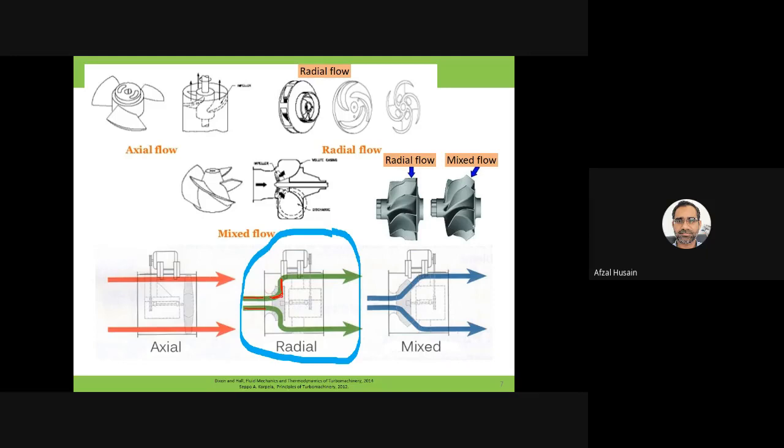Leaps out radially. So the fluid entered here. Now the fluid is here. When the fluid has entered here, until now there is no striking of the impeller. It strikes the impeller in the radial direction and leaps out in the radial direction. Is it clear to you?